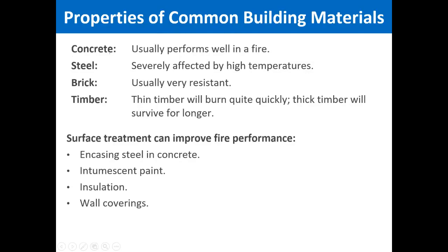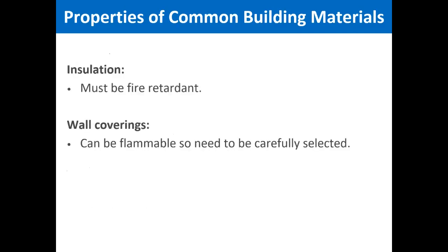Okay, there are some building materials and their properties. Concrete usually performs well in fire. Steel is severely affected by higher temperatures. Brick is usually resistant to fire. Thin timber will burn quite quickly, and thick timber will survive for longer. Surface treatment, basically, can help improve the fire performance as well. Insulation, obviously, can help prevent fires, and wall coverings should also be provided. It should be fire retardant.